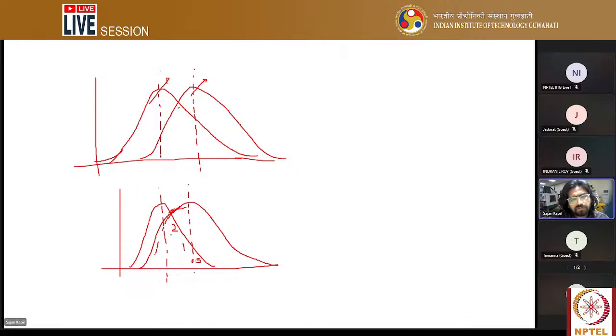There will be 2 plus 2, here 1 plus 1, here 0.5 plus 0.5. So the total energy falling onto the bead will increase, and this valley will fill up like this, because the overlapping zone increases the available energy for curing the part, and hence it will become flat.